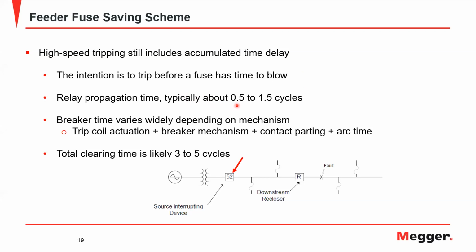It's going to run between 1/2 and 1.5 cycles depending on the relay. The newer relays hitting the market now are getting a little bit faster than this. They use static outputs and they can switch on. I've actually seen one down now to 0.2 cycles. I don't know how common that's becoming, but it is something that's breaking into the market.